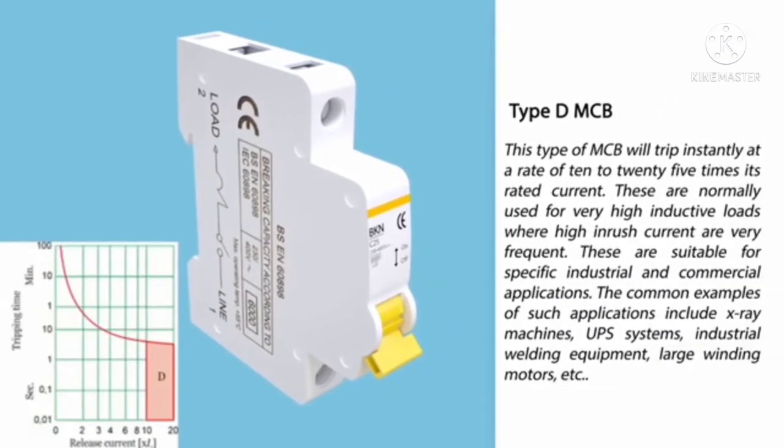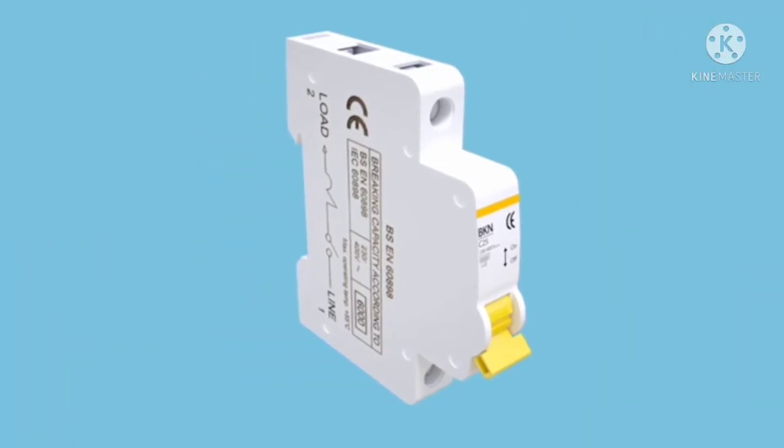Okay, and the next is type D MCB. This type of MCB will trip instantly at 10 to 25 times its rated current. These are normally used for very highly inductive loads where high rush currents are very frequent. These are suitable for specific industrial and commercial applications. Common examples include X-ray machines, UPS systems, industrial welding equipment, large motors, etc. So I hope all of you understood this MCB.